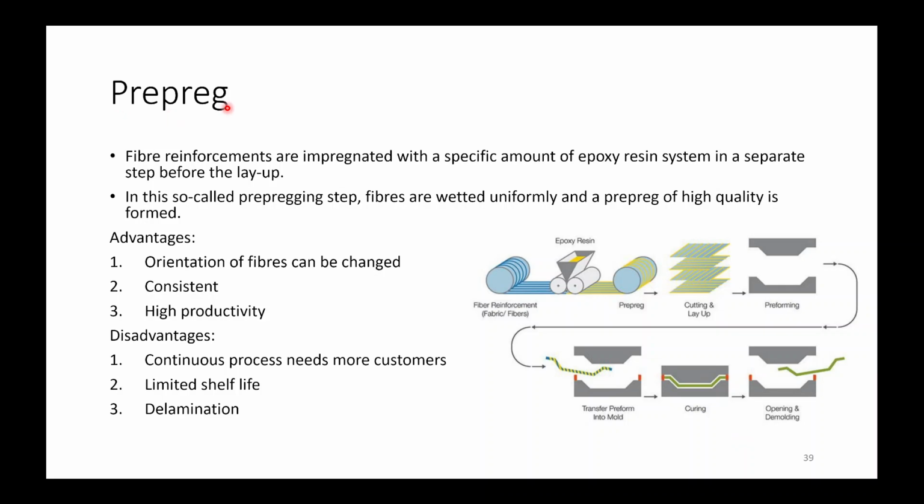Now pre-preg. In this case, fiber reinforcements are impregnated with a specific amount of epoxy resin system in a separate step before the layup. So here these are fibers.